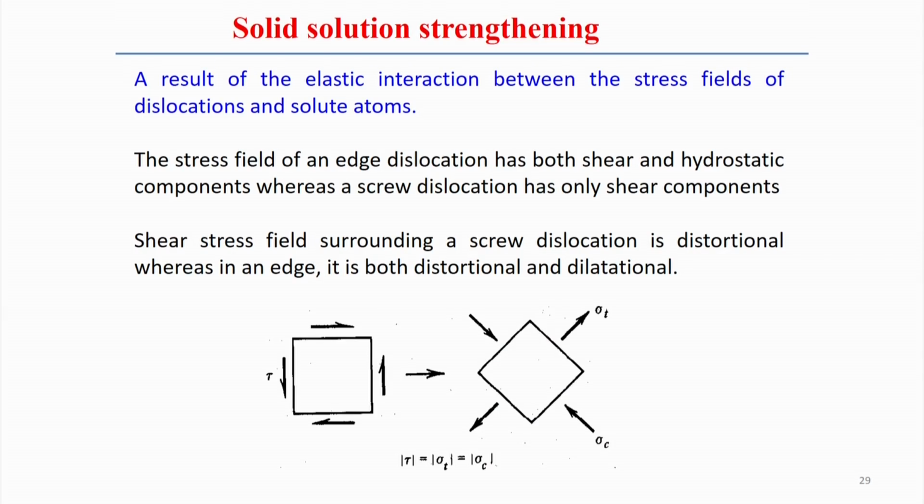So all the description is actually based on this phenomenon, how the movement of the dislocation can be restricted. Now to do that, what may be the interaction between the stress field of the dislocations and the solute atoms is responsible for analyzing the mechanism of solid solution strengthening or solid solution hardening.